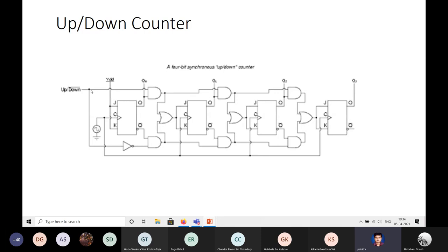You can choose a mode of the counter, just like a ripple counter, depending on whether you go up on the rising edge or the falling edge. If you use a JK flip-flop or a T flip-flop, the falling edge gives an up counter and the rising edge will give a down counter.